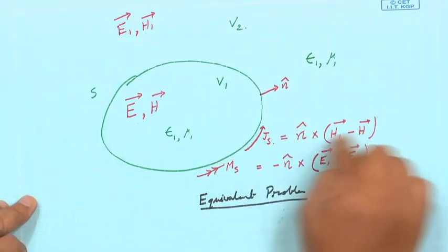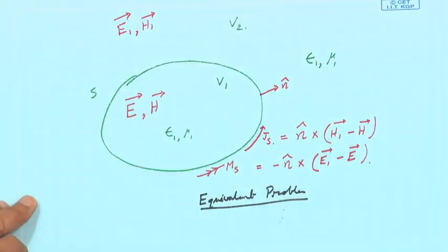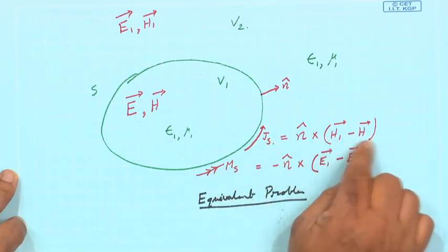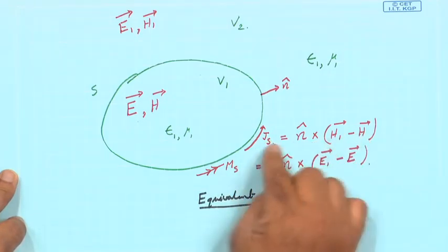Suppose in a horn antenna there is no discontinuity in the magnetic field, but there is a discontinuity in the electric field. Now, we were taking Fourier transform and all this, but think of the open ended waveguide or horn antenna, that there is an aperture. So, there is a certain field going, suddenly the electric field is getting changed. So, that discontinuity we will have to take, and that is why this introduction of magnetic current. So, magnetic current is hypothetical, we are not saying there is a flow, but the tangential component discontinuity of the electric field we are calling magnetic current, and the tangential component discontinuity in the magnetic field we are calling